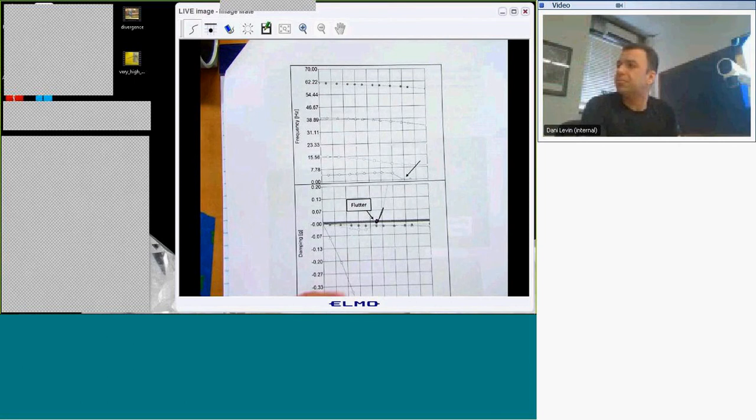The eigenvector will tell me how much of the first structural mode I have, how much of the second, how much of the third. And by the way, there are phase shifts, so these are all complex numbers in general. There's both a real and imaginary part, which corresponds to in phase and out of phase components of the modes. So you can find the actual shape.